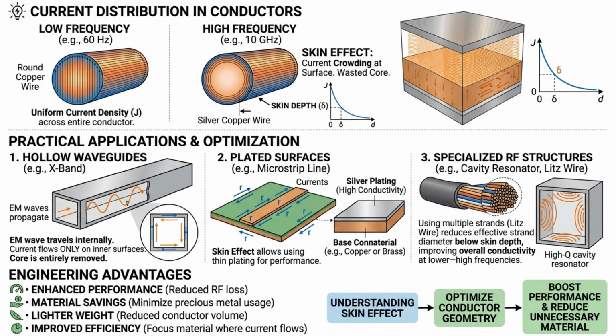At higher frequencies, conductor geometry becomes extremely important. Hollow waveguides, plated surfaces, and specialized RF structures are practical because current naturally flows near the conductor surface anyway. Understanding skin effect allows engineers to optimize performance while reducing unnecessary material usage.